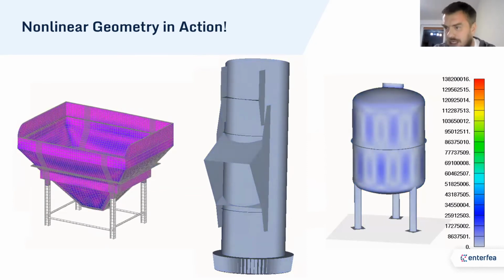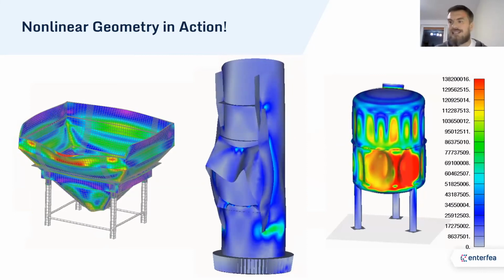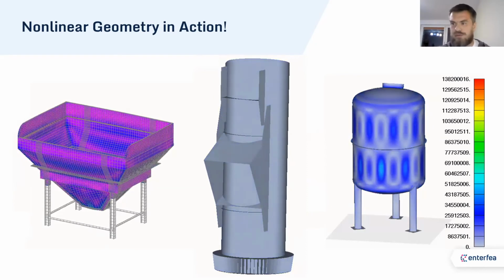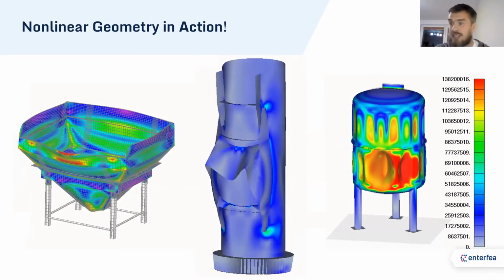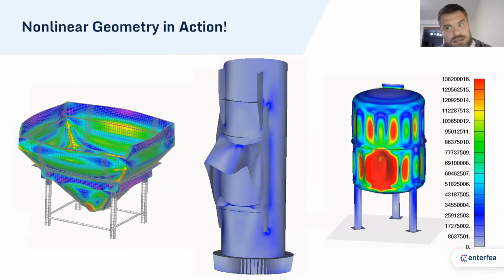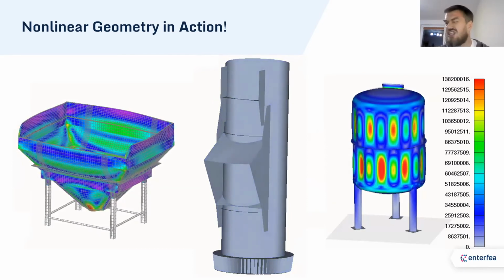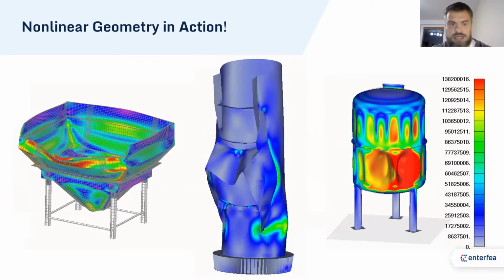of complex structures. And that's the thing, because when buckling is easy, there is a simple equation governing it. You can fill it in, use your structural code of choice, press play, and you know the answer. You can have a spreadsheet in Excel that calculates. But when things become complicated, it's getting complicated really fast, to the degree that it's actually more or less guesswork, unless you're doing a nonlinear FEA.